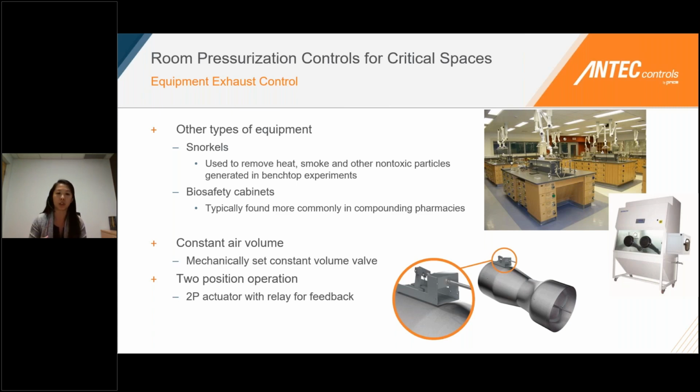And then if you flip that switch off, you can have that valve turn down to its minimum position based on the hard stop on the minimum side. So in both cases, you don't need a controller, again, because this valve is mechanically pressure independent. It's going to be able to maintain the airflows at each of those states, regardless of the duct static pressure.